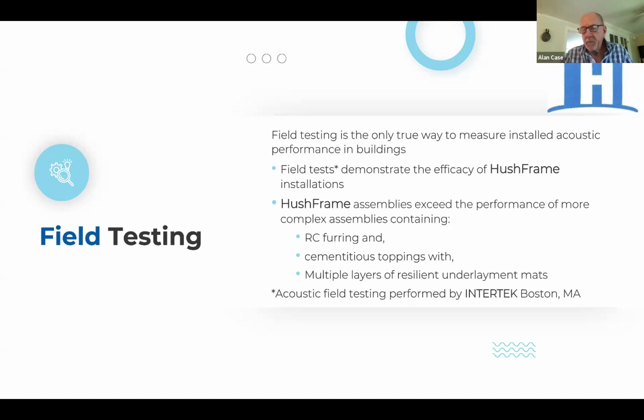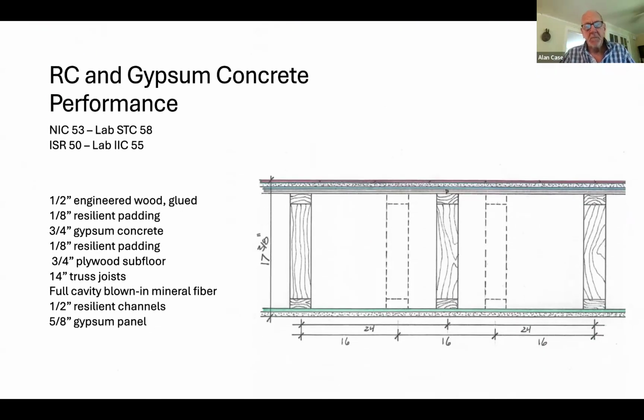It's also project delay. Put down a cement floor like that on top of the wood frame. You have to empty the building completely. You've got to pour it. You've got to let it dry. You're introducing all that moisture into a wood building where you're bringing in potentials for mold and all sorts of things, and it's just so disruptive. Just having to empty the buildings down and vacuum them to do this is so ridiculously disruptive that it's one of the things that the wood frame guys want to get away from first: how do we get away from gypcrete? How do we get away from these toppings that are just clogging the works?